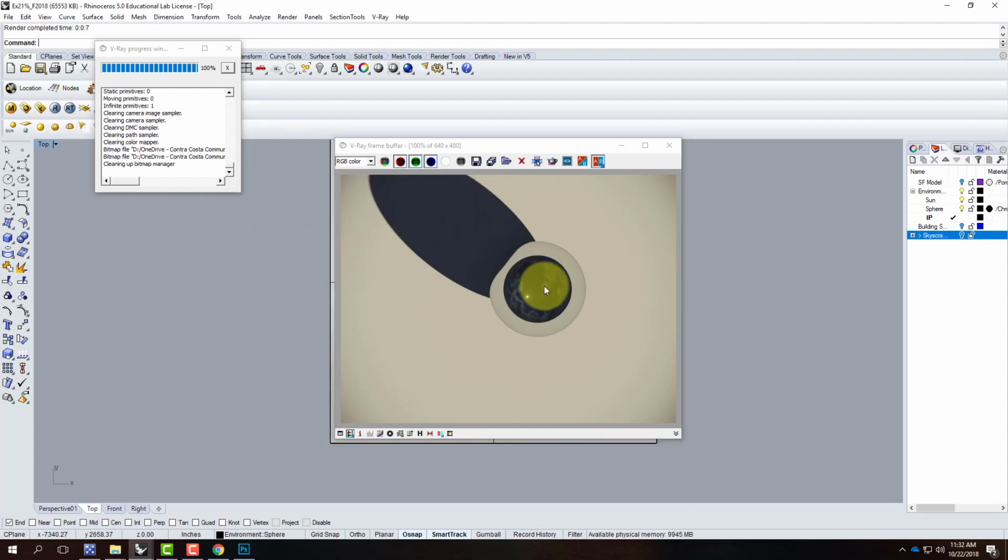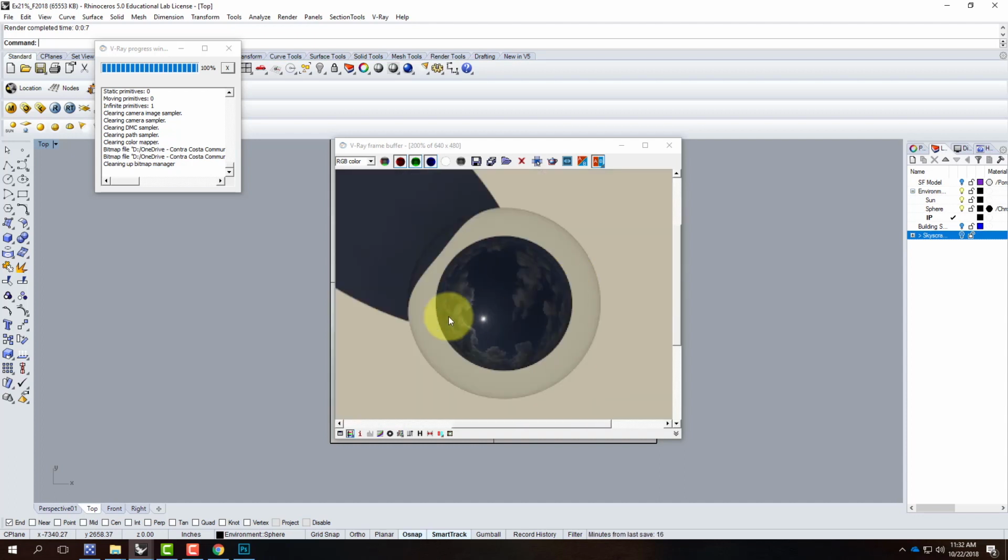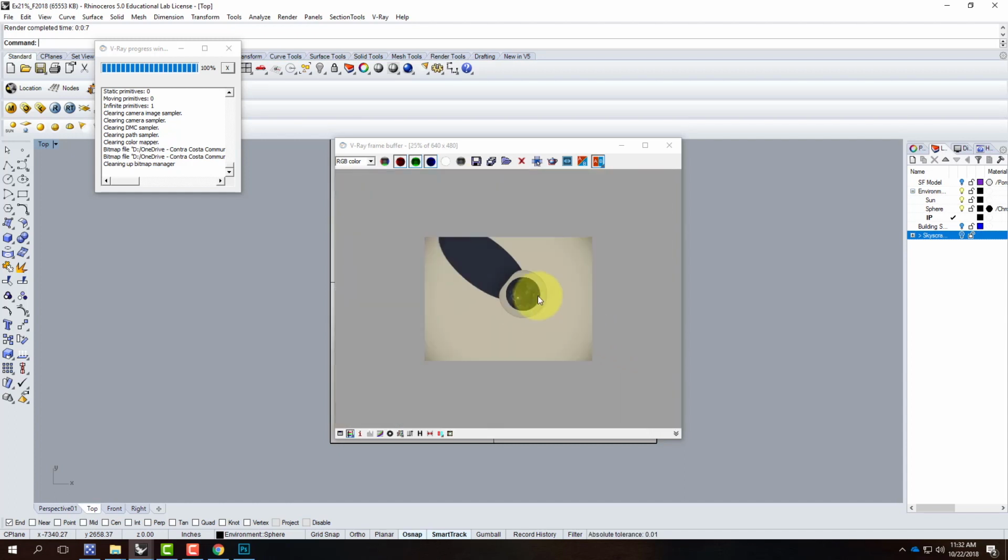So now that I've done this render, it's a little bit dark. So I could change my exposure just a little bit to brighten it up. And I'll do that for the next one. I'm going to look at a couple things. One, I'm going to look at the reflection that's inside of my glass sphere, right here, or my chrome sphere. In that reflection, I can see where the sun is as I'm looking up at it. I can also see where the sun is casting a shadow from that sphere right here. So in this case, the sun, if it were in fact where it was supposed to be, would be casting a shadow over here. So the time of day that my sun is set for is not correct for the time of day that the image is suggesting. So I need to make one or the other match each other.